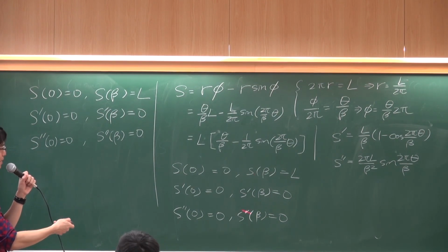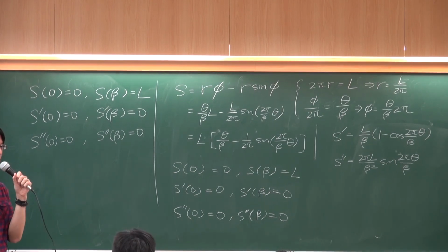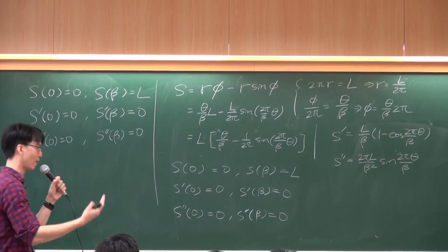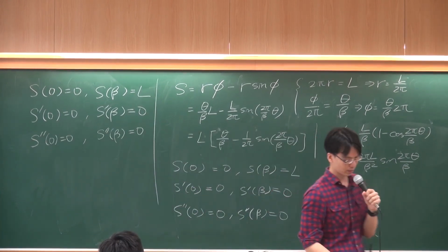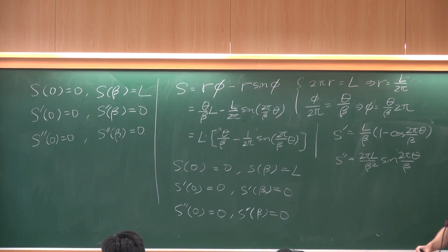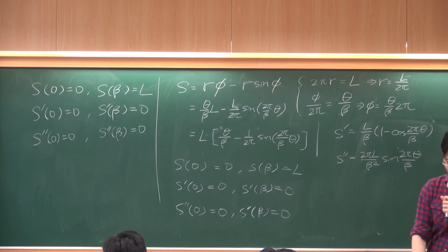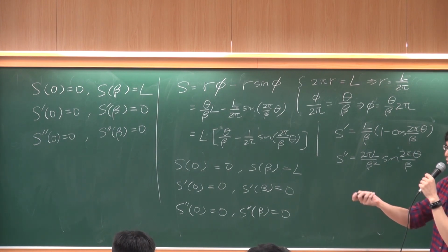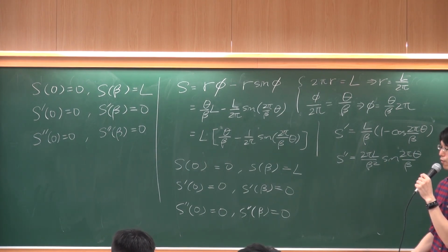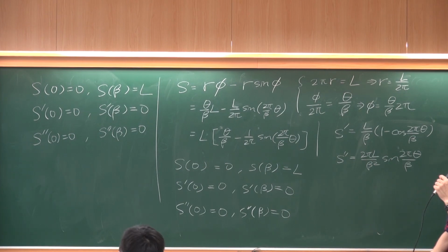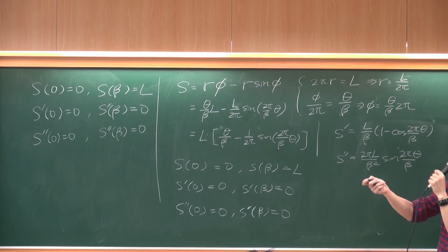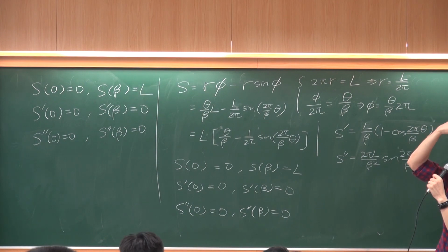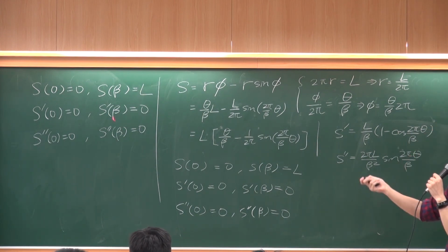So by far, this one is the best because it satisfies all the 6 conditions. We finally found a curve that can satisfy all these 6 conditions. You can take a look at the curve. They don't go to infinity, even with the jerk. So next time we'll talk about the polynomial motion, and we'll also see if this one can satisfy all these 6 conditions.